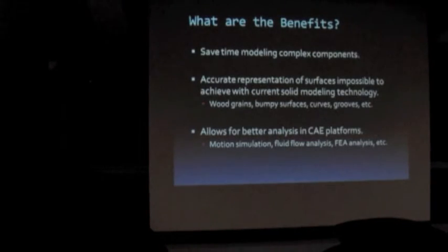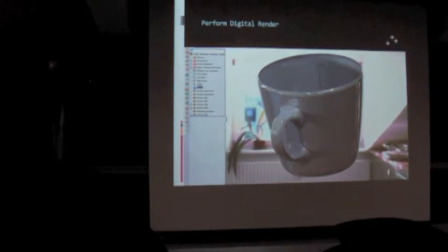So does it have any thickness to the wall, or is it? There is a little thickness. What you can do is a post-processing technique of increasing the thickness, just like you would on any solid model that you create off of just a 2D object. It's the same property.